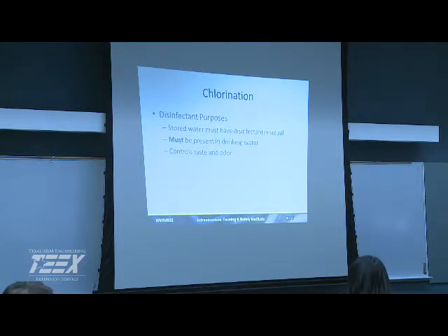One of the good things about chlorine, and y'all aren't having to really deal with it, is taste and odor. If you're on groundwater, you normally don't have taste and odor issues. If you're getting it wholesale, you're not having it either. But if you're pulling surface water, chlorine is a good way to get rid of it. The problem is if you're chlorinating at the head of your process, you can potentially be building disinfection byproducts. So you wind up with a different problem. You're taking care of one problem and creating another.